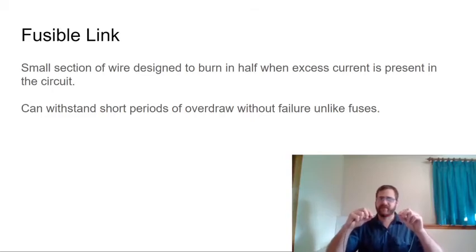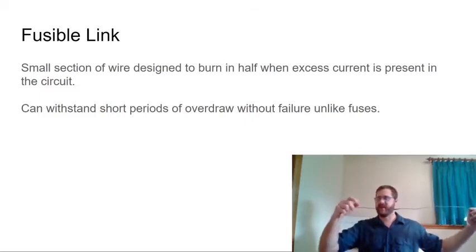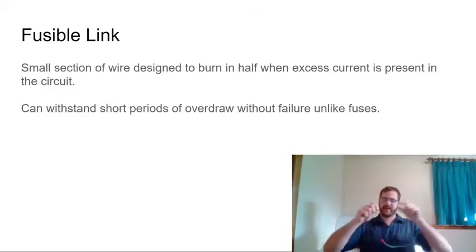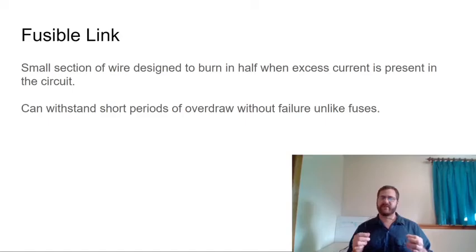So you'll have your fusible link hooked directly to the battery or very close to the battery, and then it connects, and it protects the wire that feeds power back. Usually it's pre-fuse box. So you'll have the battery over here, fusible link right off the battery, and then a wire that runs back to the fuse box area. Those are used to protect wires before they go into a fuse box where a bunch of fuses are.